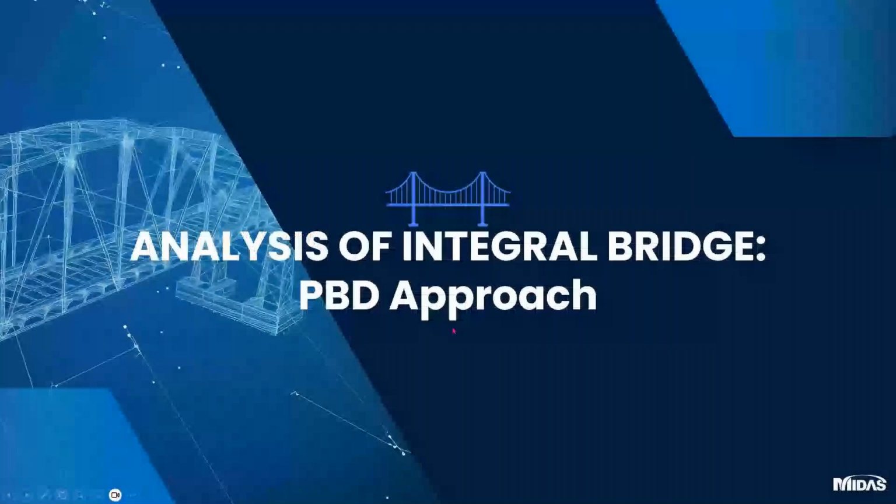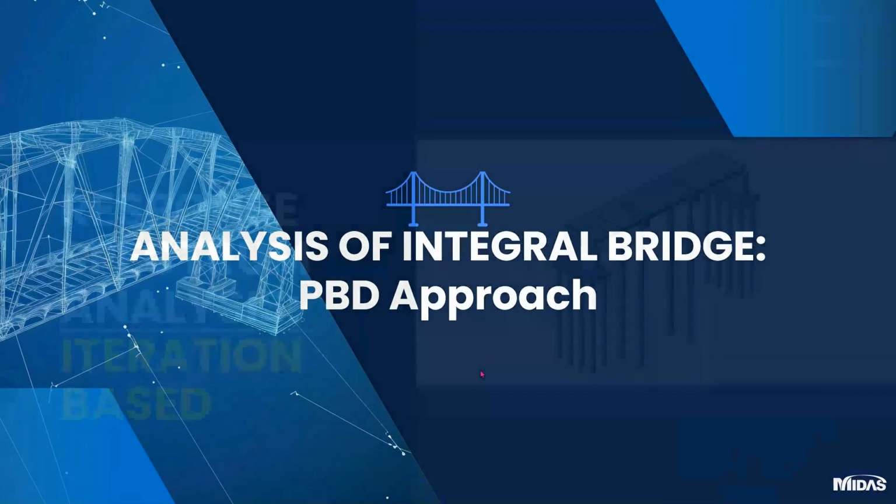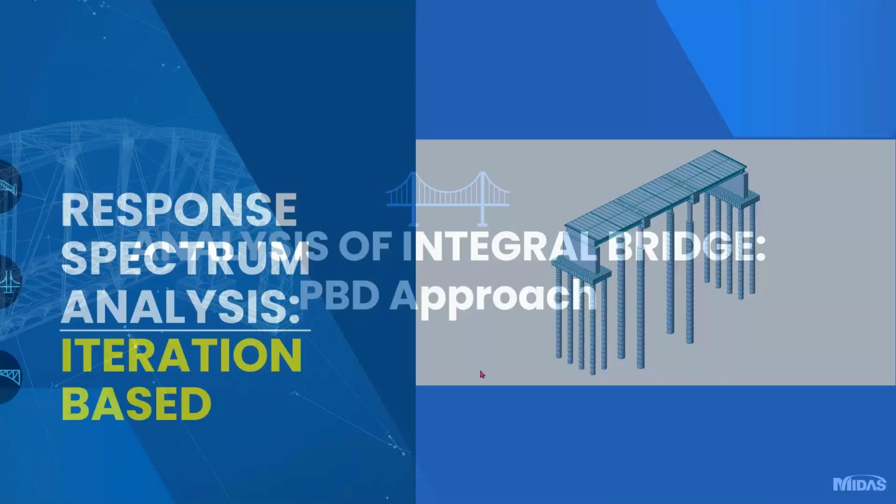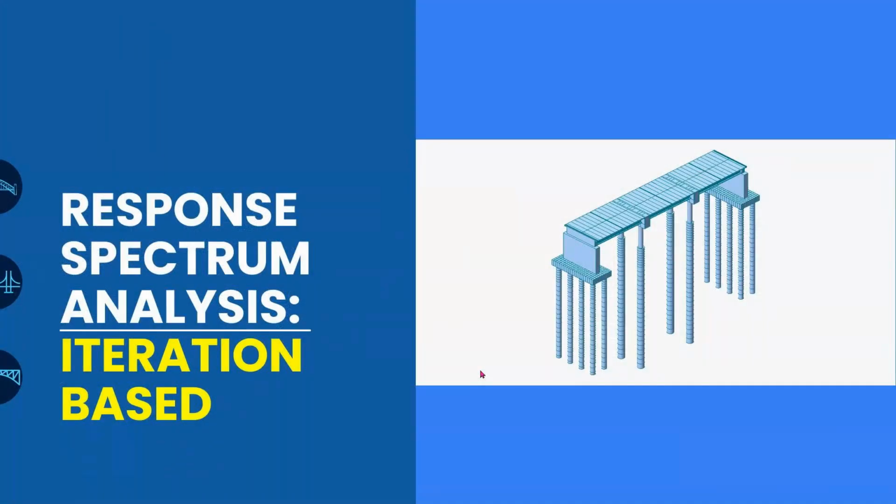So with this small background, let us now focus on the analysis of an integral bridge with a PBD approach. As I said, response spectrum analysis will be covered in this section, and we will do certain iterations to see that the soil spring deformation is within the limits.